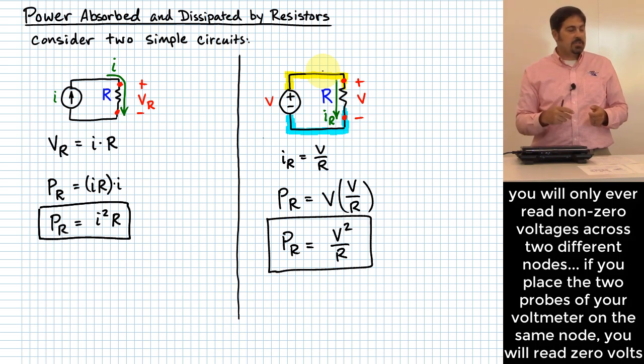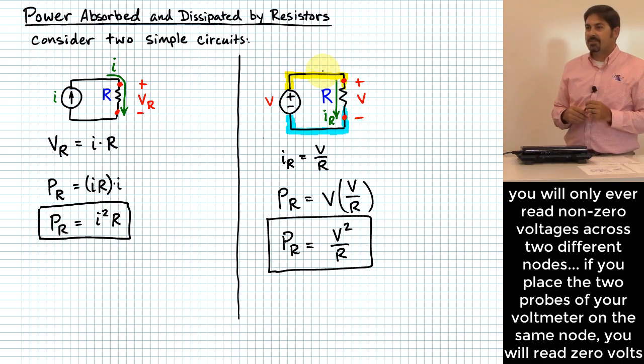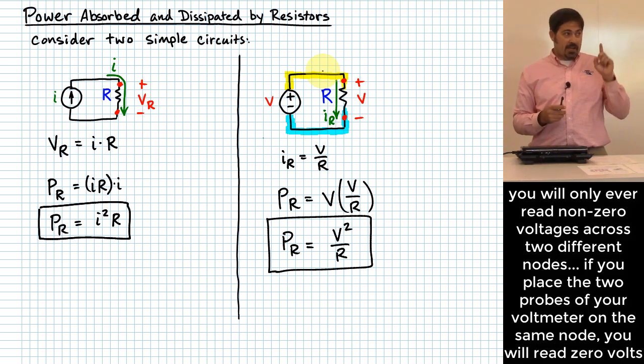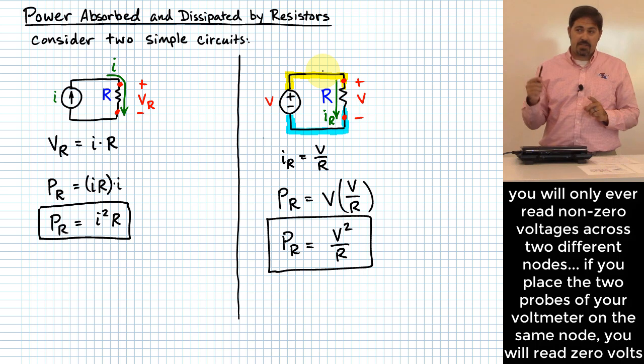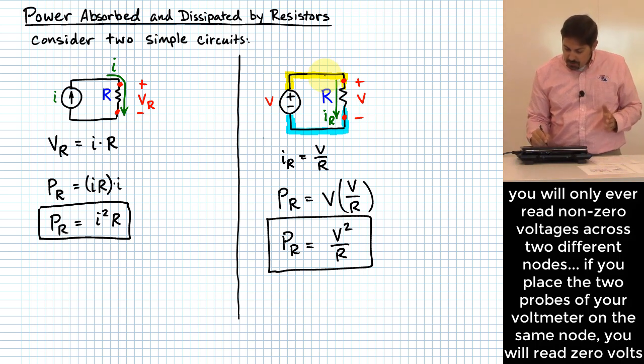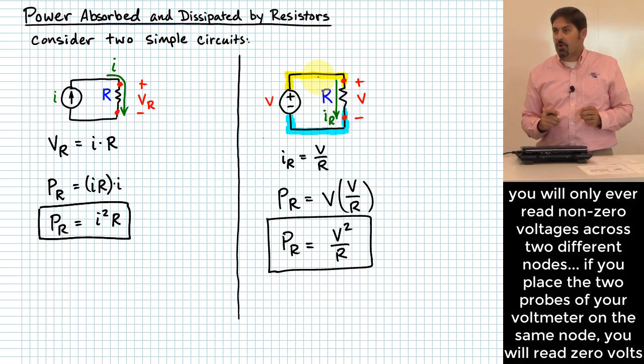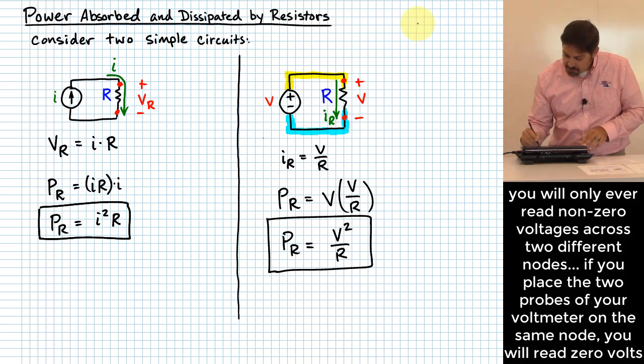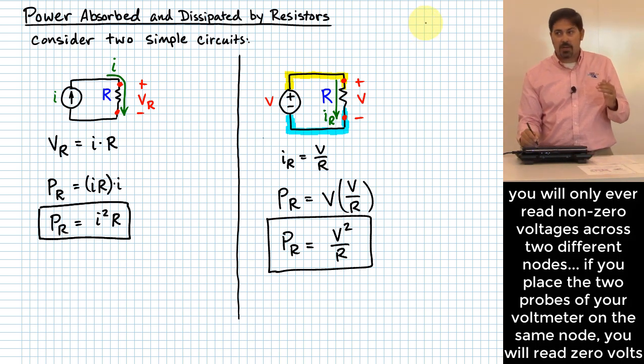You'd expect it to read 0 volts. Why? Okay, there won't be any voltage drop. We can actually think to ourselves why that's the case in terms of Ohm's law. Okay, I said a second ago, we are going to assume all of these wires have 0 resistance, right? So that essentially, if the wire is 0 resistance, that means V over I equals 0. Okay? If V over I is equal to 0, what's the only way that can happen?